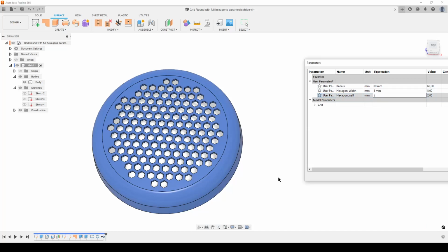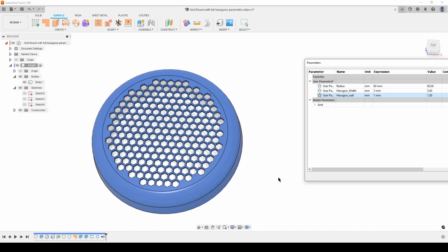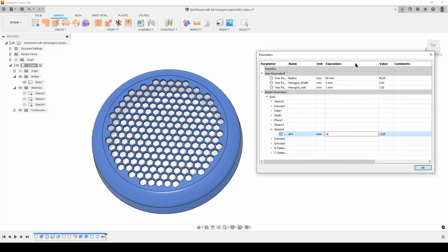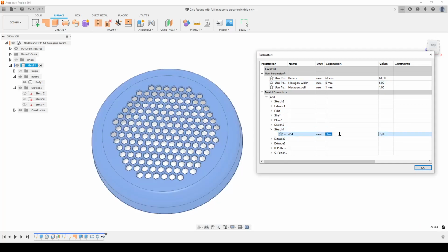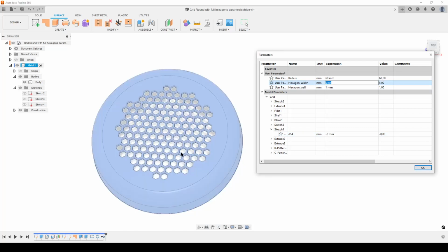And of course, you can edit the sketch creating the surface part, which we have here. We can do that in here. Let's see, that must be that sketch. We have an offset here. Let's change that to -5 and just click somewhere outside. This means the hexagon should be moved more towards the middle. Yes. Oh, I need it -8. Tinkering with parameters is fun. Like that.